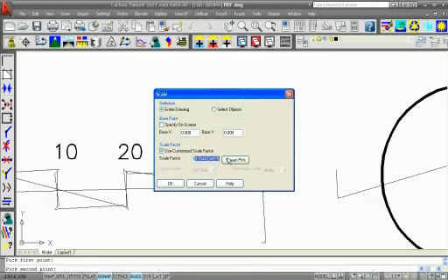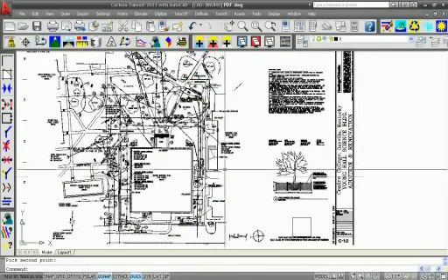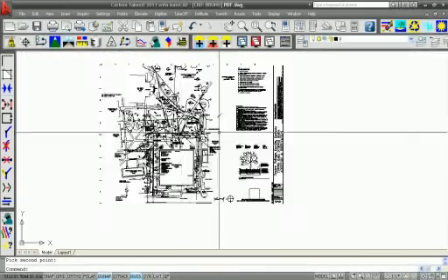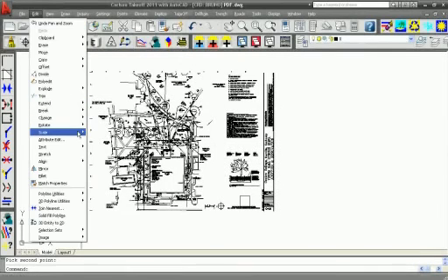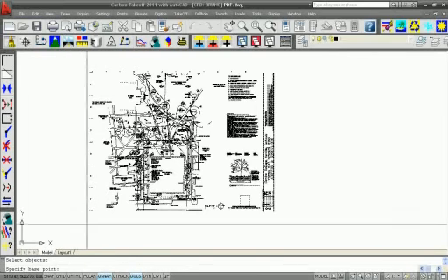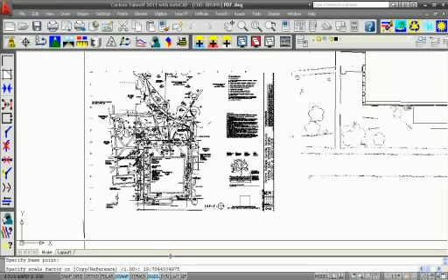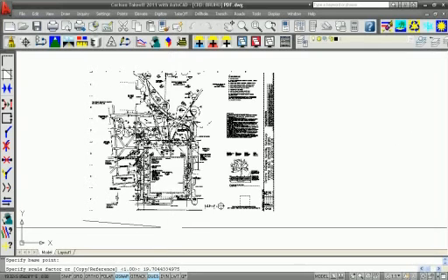Just for time purposes, I'm going to use the other scale. I'm just going to copy the scale and say cancel. The 2D scale can take a long time to convert a drawing this complicated. So I'm just going to use the AutoCAD scale and use that factor. Okay, select objects, base point, and paste in that value. Okay, and hit enter.